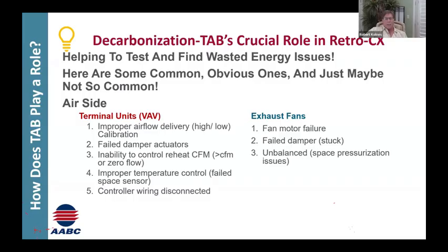Types of examples that I see out there nearly 100% of the time are associated with the calibration of the controller, the operation of the damper, the reheat coil face may be impacted with insulation. That happens quite a bit on systems where you have some internal duct lining.